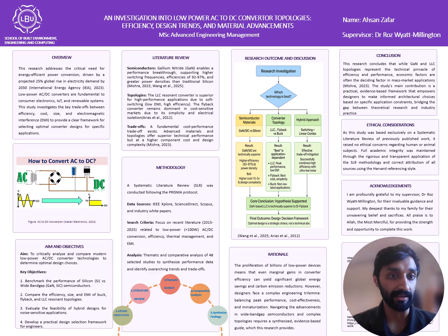Performance versus simplicity is the second point, where buck converters are simple and efficient, but they do not provide isolation. Flyback converters provide isolation and low cost, but suffer from EMI. LLC converters give the best performance, but they are more complex to design. Then we have thermal management. Wide band gap devices like GaN operate at high frequency. This creates hotspots in small areas. Thermal management is essential to ensure reliability.